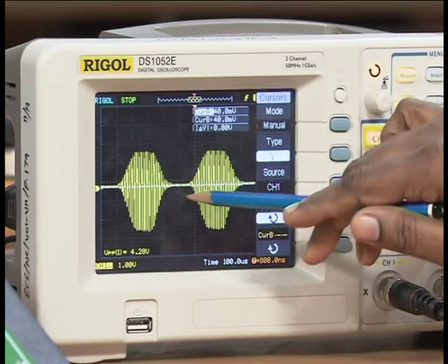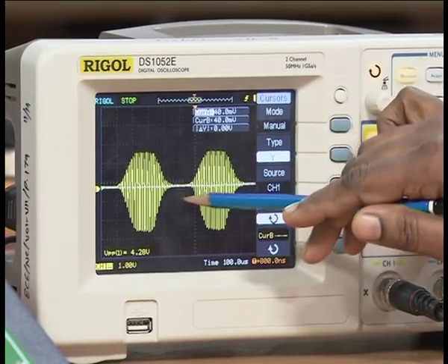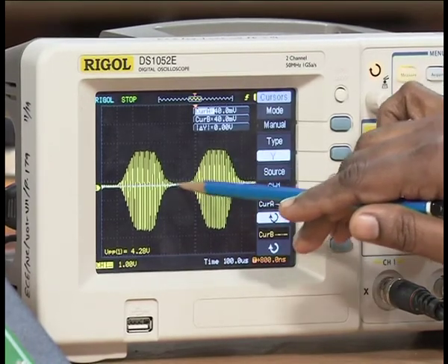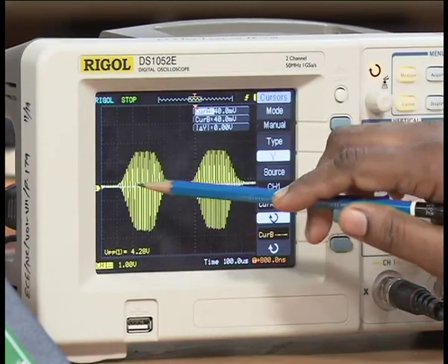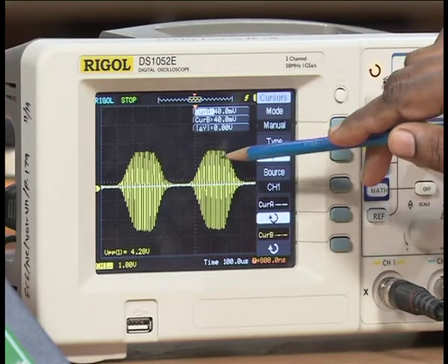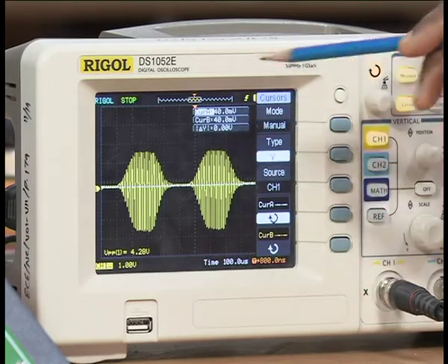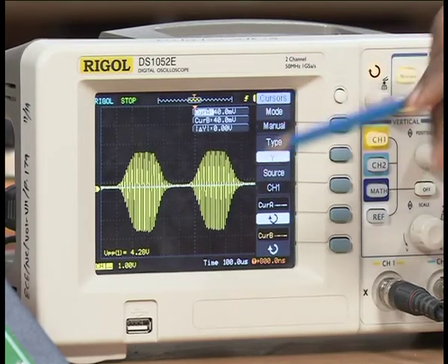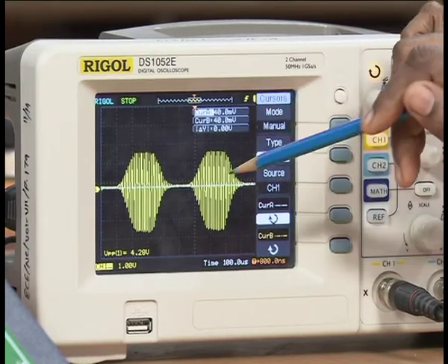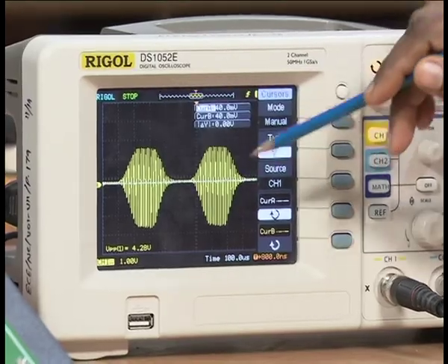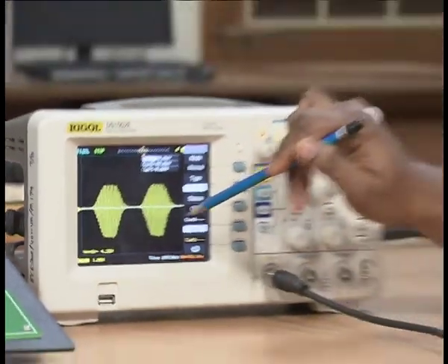So, here you will have phase reversal. Here you can see the phase reversal part of the over modulated signal. The envelope tracks a voltage that is not equal to the message signal. So, for AM modulation, we need to keep the message signal amplitude always less than the carrier signal amplitude. This is how we measure the modulation index of the AM modulated waveform.